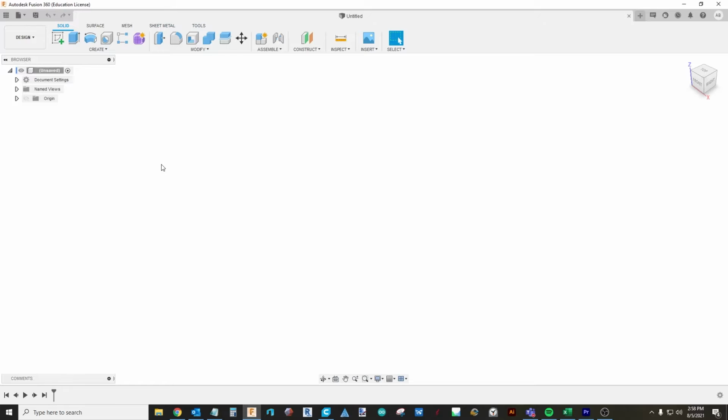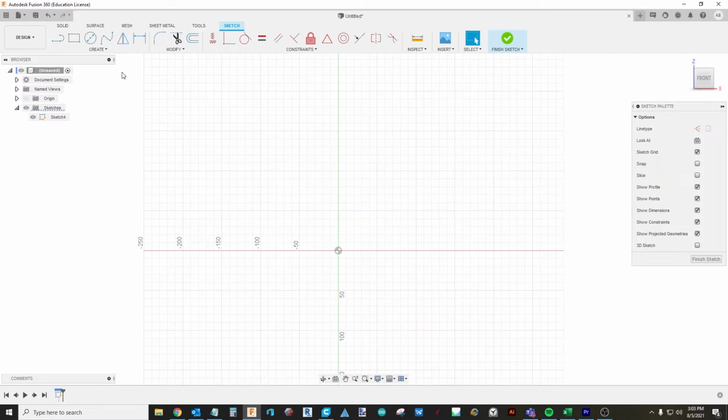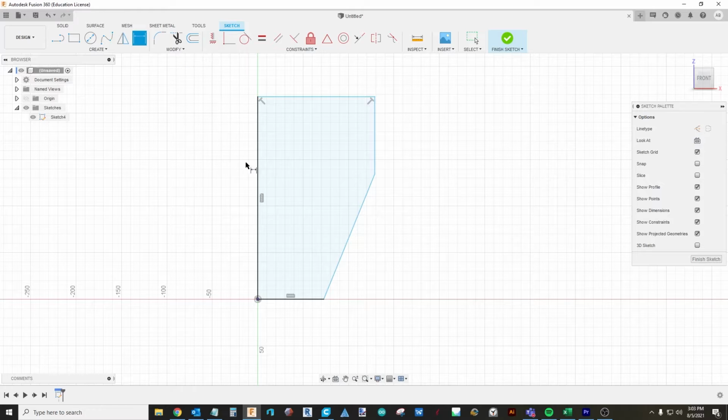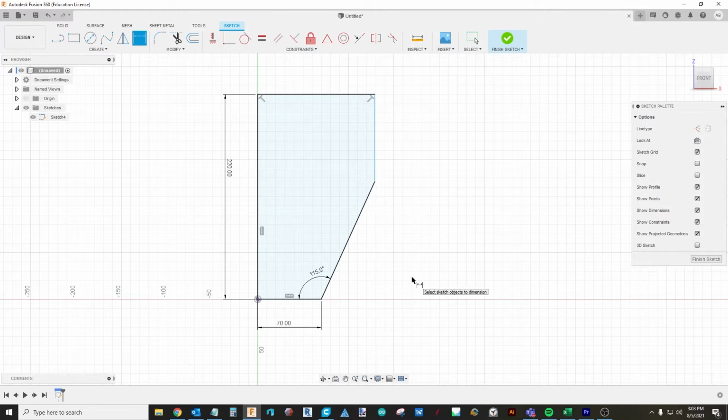At the core of this process, sketches are used as the most basic building block to define shape and size. We create sketches on planes. This could be one of the origin planes, a user-created construction plane, or a flat face on a body. We have many sketching tools, with some of the most basic being lines, rectangles, and circles. We can constrain and dimension these in relation to each other to fully define our sketch.